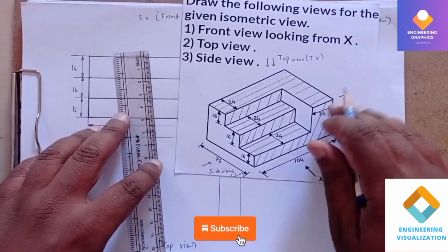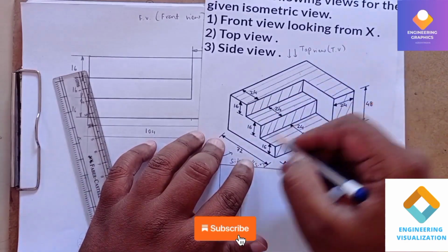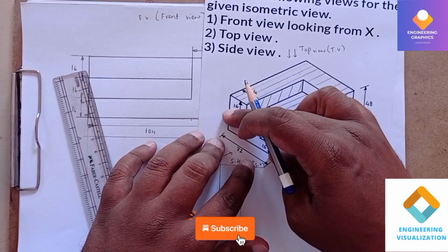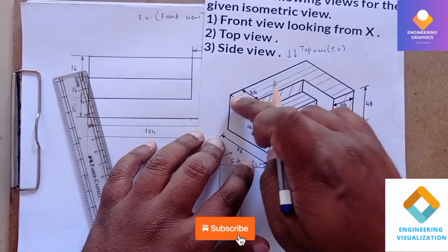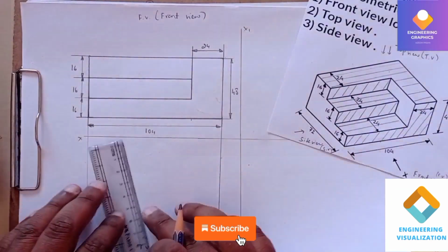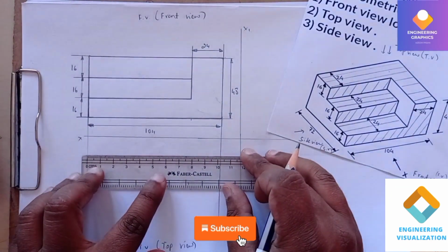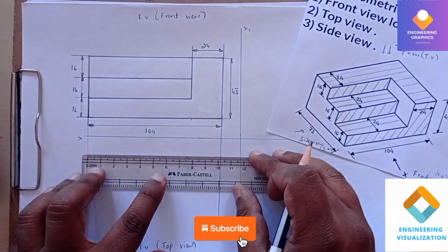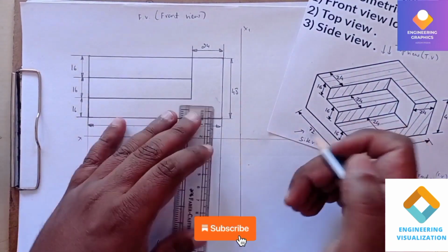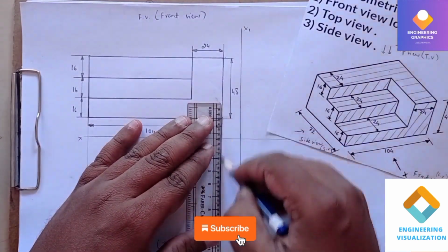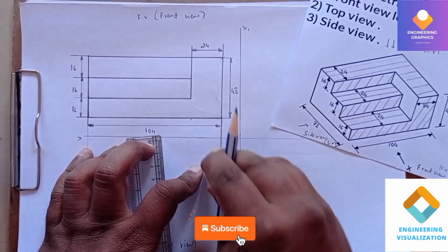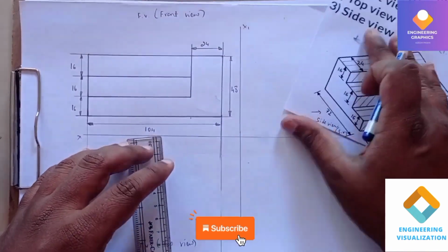You can see, it is having a length of 104, and then it is having a width of 72. 104 by 72 we should construct a rectangle here. First I will construct that 104, and then I will take 72. Okay, so 104 we already have here. So you can just draw a line. So draw the lines straight so that we get the exact dimensions. Okay, make sure you draw the straight lines.